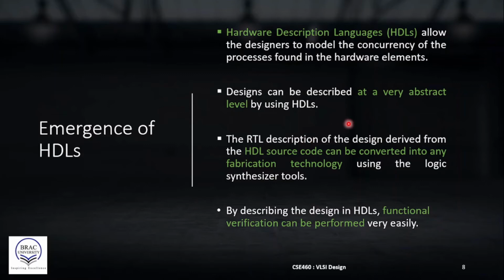or the register transfer level description, which basically means that the circuit specifications written in HDL can be directly converted into actual hardware registers with interconnects. This RTL description can later be used for logic synthesis and functional verification.